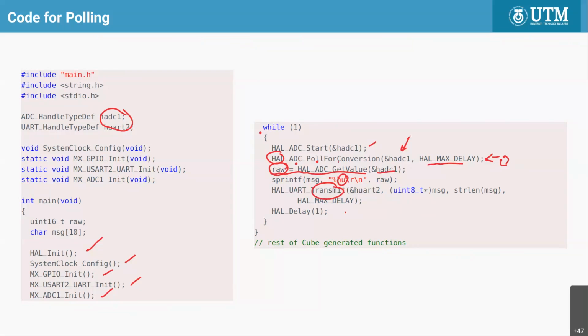And then we have some delay here, you must have a delay. Normally for any of this IO, you must have a delay. If one doesn't work, maybe put 1000 or something. More like a trial and error. You don't force the I/O devices to work immediately. Sometimes it's not capable of doing that, so just add some delay there.